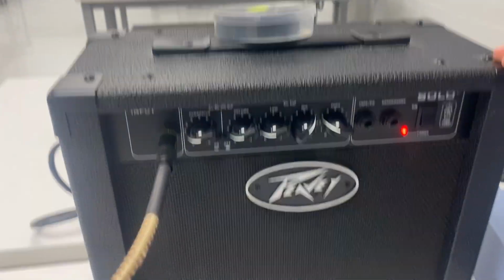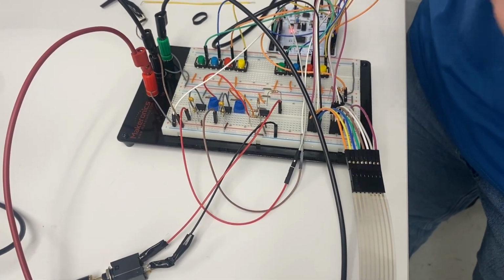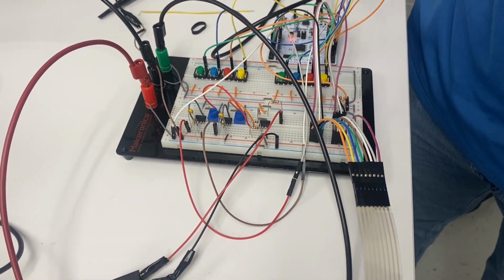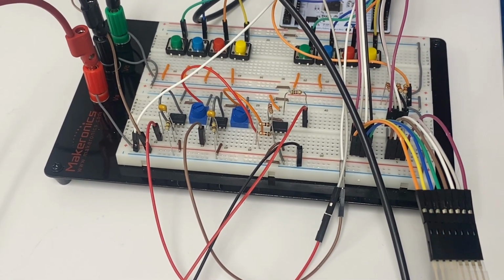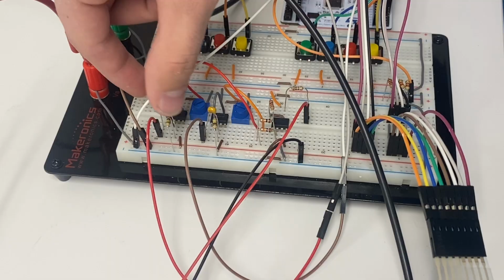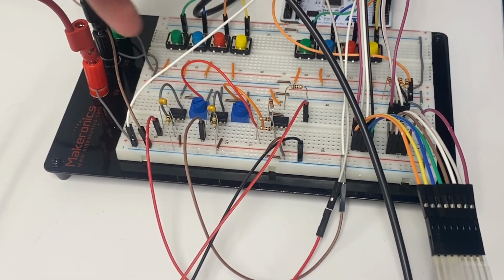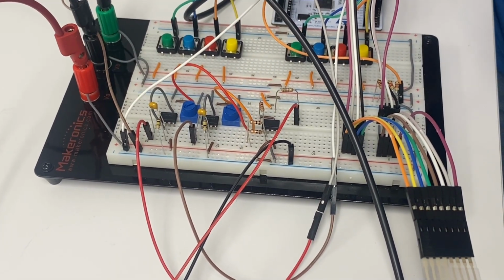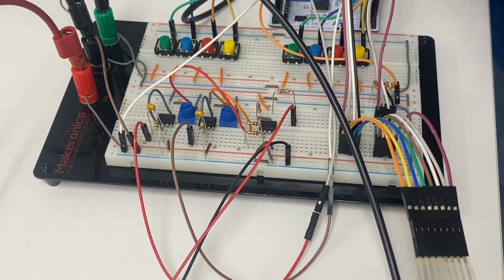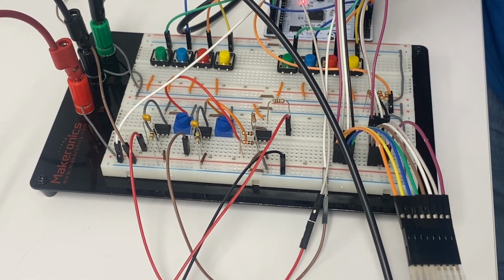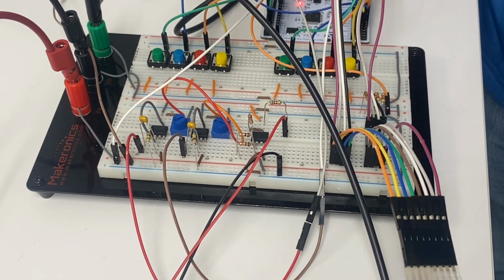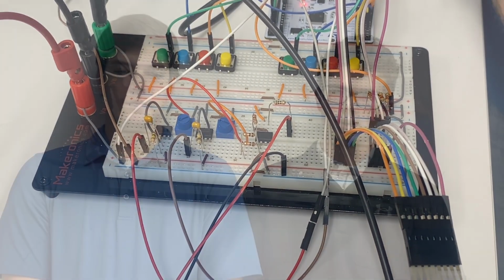In our original design requirements, we had talked about removing that DC offset using a differencing amplifier to subtract out the DC offset, but by using the simple RC filter and then a buffer, we were able to remove that DC offset without having to figure out ourselves how much of an offset it would be. So we didn't have to be as precise. We could just let the filter do the job. So all in all, we were able to meet all of our design requirements that we specified in our document.